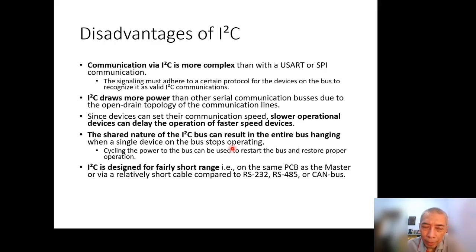Okay, but we have a solution. You can cycle the power to the bus to restart the bus and restore proper operation. And then, I2C is designed for fairly short range, maybe on the same PCB as the master or via a relatively short cable, compared to USART or RS-485 or CAN bus.